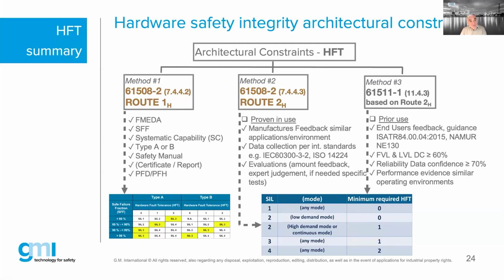We call this mode of degradation. I know some end users who mistakenly remain in the 2 out of 2 voting block and are actually saying that, oh, we will just bypass or disable this one input and we will keep the voting block as a 2 out of 2, which in my opinion is a very serious mistake.